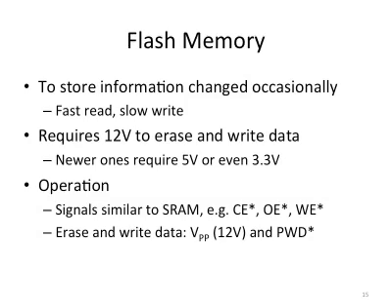Flash memory is very popular nowadays because it can retain information even after being powered off. The benefit of using flash memory is that it can support very fast read speed, but on the other hand, if you want to update the content, to perform a write operation to the flash memory, the speed is quite slow compared to the read.